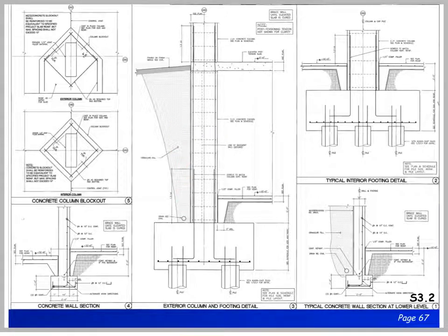Other items that I would like to mention: note how the use of a dashed line to indicate the building wall beyond the column, while the same dashed line is being used to indicate ties around the rebar, while the rebar is shown as a solid line. This multiple use of the same type of line is all part of learning to read drawings and interpret information. Also, we have an auger cast pile that is going down deep into the ground, showing it as it continues using a cylindrical broken line.